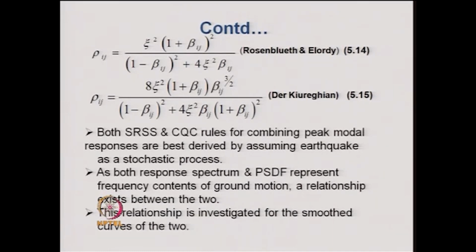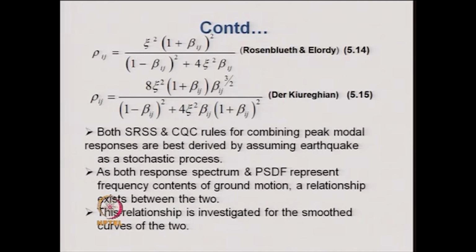Using those principles, one can justify the combination rule that we classically use for combining the modal responses in the response spectrum method of analysis. Now, as both response spectrum and the power spectral density function represent frequency contents of ground motion, a relationship exists between the two.